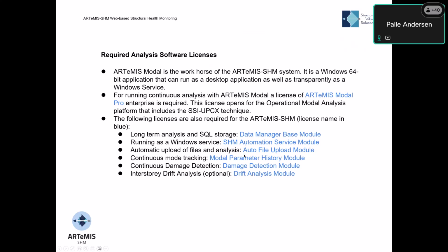This module allows ARTeMIS to scan the different folders and automatically load data when something is being saved by the data acquisition system. Then regarding the analysis, there is the continuous mode track, mode parameter history.